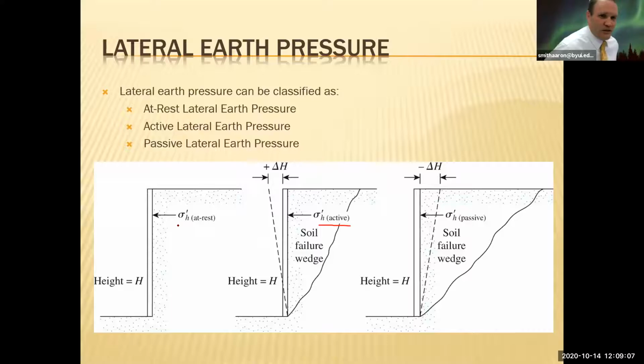The at-rest soil condition is typically when you have flat ground and there's no retaining wall. So if you see a retaining wall, you can just assume there's probably some active lateral earth pressures involved. If you had to assume, you would assume active.